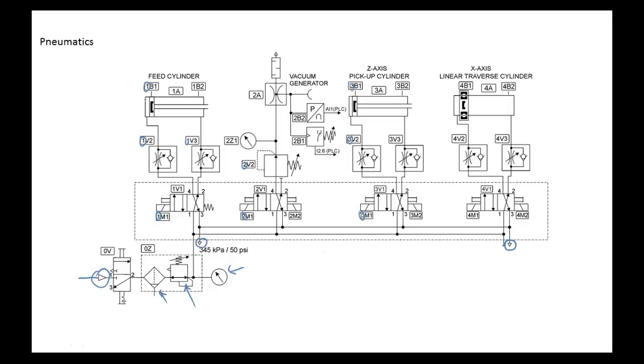And the problem is liquids don't compress and air does. So the amount it holds depends on the amount of cubic feet. So what happens is that when you compress air, it can't hold water anymore. So what does it do? It releases it. So if you're going to run pressure that high, you've got to have all types of moisture removing devices out there, using chillers and all kinds of stuff.